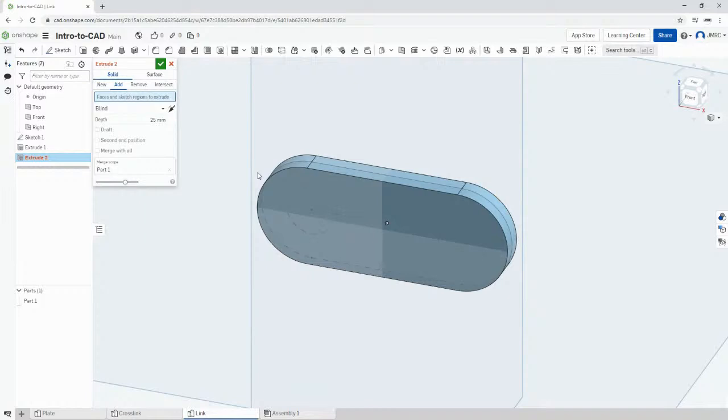And our intent or target is to select that circle. And this face is currently blocking our objective of selecting that. So to select nested items, it's simply right-clicking. So notice here we have this menu, and simply selecting Select Other.